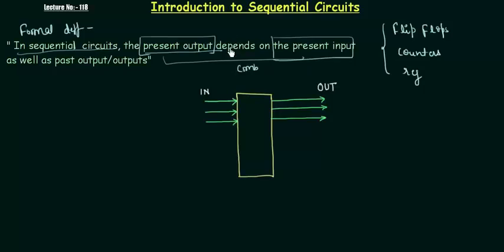We have to use the word only here for the combinational circuit, because say I have a combinational circuit that takes two inputs. The first input is, let's say, 1, and the second input is also 1, and the combinational circuit here adds these two numbers. So 1 plus 1 gives you 0 as the sum and 1 as the carry. Okay, so this is the result that we are having. Again, you are using this same adder, and you want to add 0 and 1, then the result will be 1 0. It has nothing to do with this output.